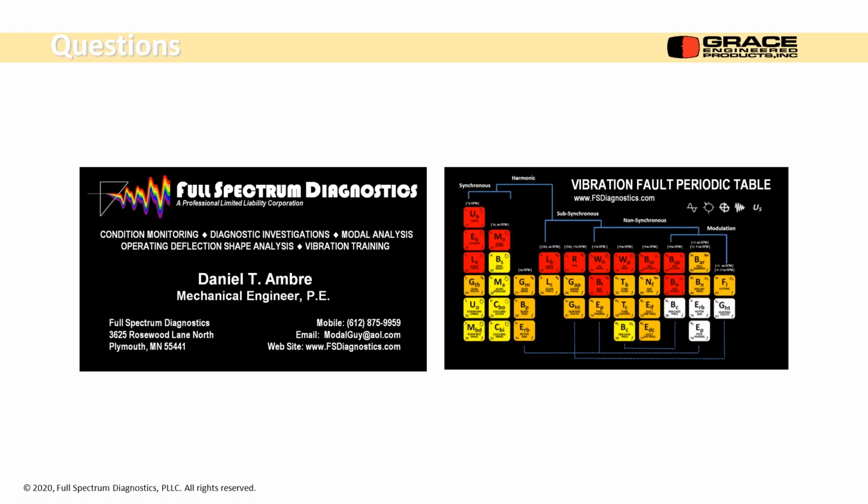When you're going in and out of the load zone of the bearing, on an inner race defect, it'll modulate at 1 times RPM. Every time it goes into that load zone at the bottom of the bearing, once per revolution, you're getting that modulation effect. And the more the modulation, the more wear or defects or spalling there is. But there are a lot of different modulations that you can look at.